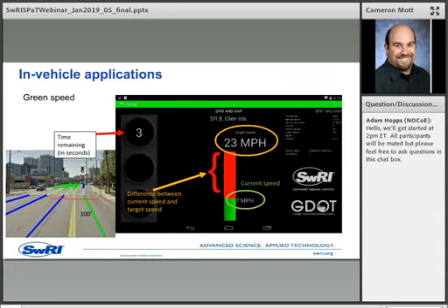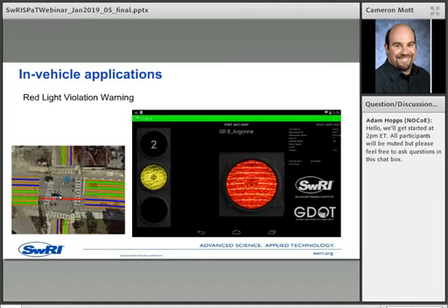and an indication of the target speed and the current speed. So this vehicle right now is traveling at 7 miles an hour, and in order to make it in the next 3 seconds, that 100 feet to the intersection, they'd need to speed up to 23 miles an hour. Now, given that's the next phase, they may want to go through it on a yellow, but it appears that this vehicle is slowing down already, and it's unlikely given this information. But we are presenting it to drivers and, of course, allowing them to make their own much more informed decisions.